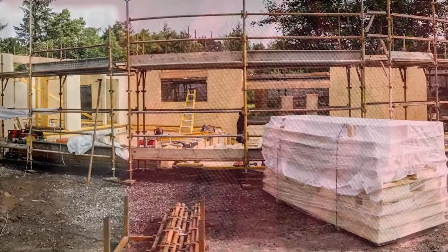Although flat roofs and low-pitched roofs are a common feature of contemporary designs, more commonly homes will have pitched roofs, and these fall loosely into two types. Warm pitched roofs, in which the insulation follows the slope of the roof itself, and cold pitched roofs, where the insulation rests on the horizontal ceiling, with a cold loft space above. Traditional UK practice has been to follow the latter model, but it's becoming increasingly common to use warm roof construction.